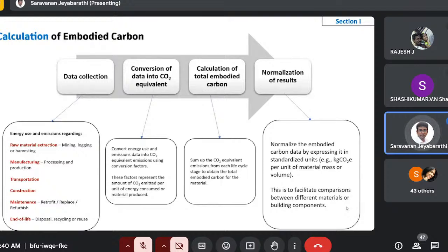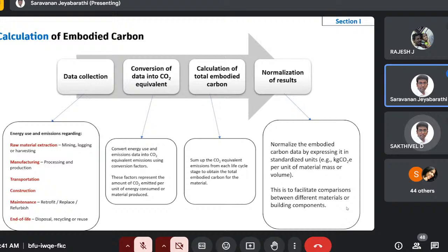CO2, this much amount got emitted, this much methane, nitrous oxide and other gaseous emissions will be there. Sometimes waste is also emitted: as a solid, some waste material would come out, and as a gas, some emissions would come. Those are all the ultimate data you should collect for calculating the entire embodied carbon of a particular product: material input, energy input, gaseous output, waste output.